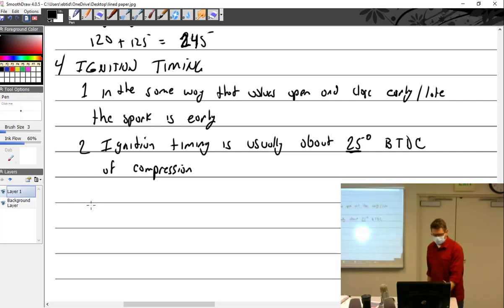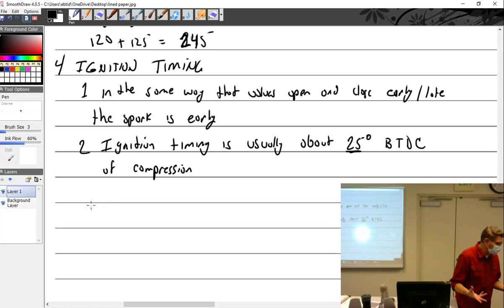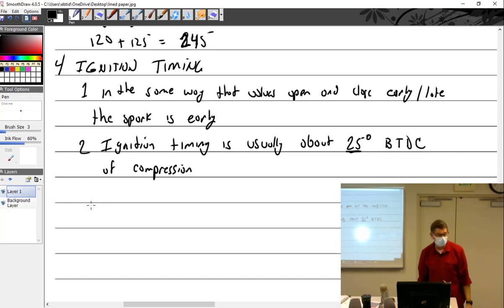Well, these guys aren't stupid when they figured this out. They're like, well, since we've got two, let's make use of it. If you shut off one of those ignition systems, you're going to see a noticeable drop in RPM because it's been designed so that the two spark plugs both ignite a flame front, and the flame fronts then move together. Instead of starting over here and going across the cylinder and down, you have it starting in two spots and burning together.